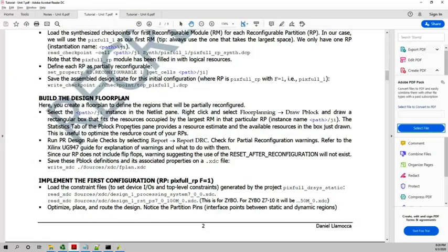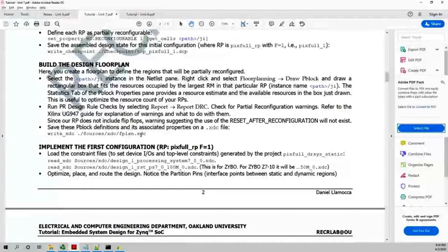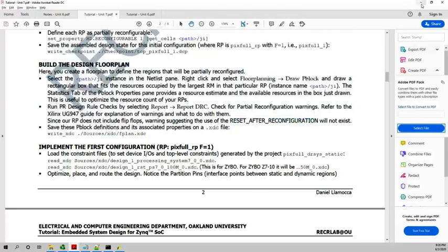All right, so I think this is very good, and now we are at a really good point. What happens if you have saved it, and now you want to reuse this file? You don't have to do any of this, and instead what you do is the following. Instead of write XDC, you just do read XDC, right? You don't have to do anything else, and everything will be loaded automatically. But you still have to do the whole process at least once per project, of course.